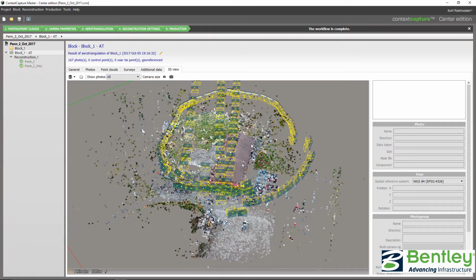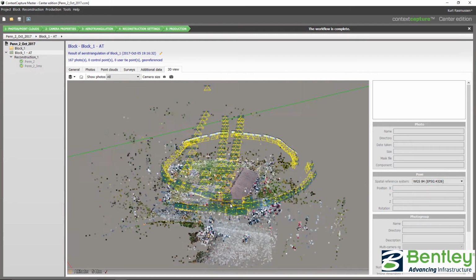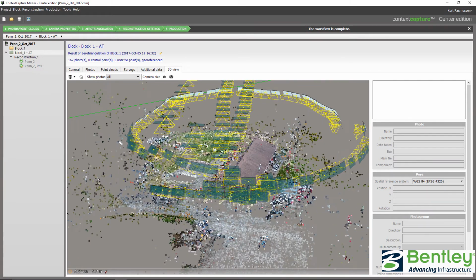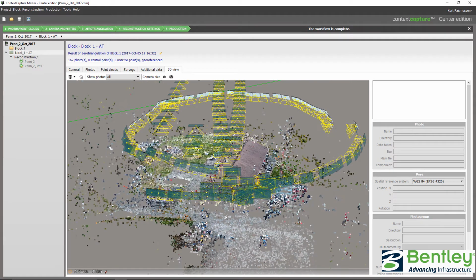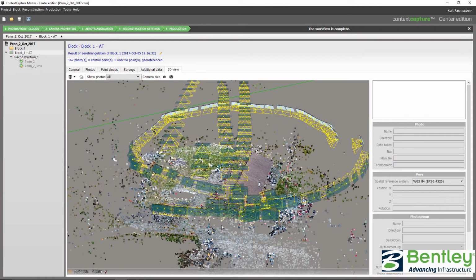Also, you're going to see that the building structure that I'm looking at is over here. I only have my obliques over here. Really, I needed to do a couple more nadir images. I was kind of fighting with sunset. It was in the evening time, and also battery life. I have about 20 minutes battery life, so I just flew this real quick. It was a real quick example, just to see the results that I got.